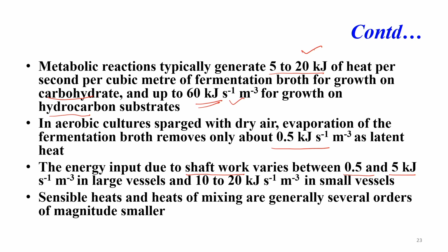So, typically the sensible heat and the heat of mixing are several orders of magnitude smaller than the heat of reaction. So, many times when we calculate the heating or cooling requirement, we can directly use delta H heat of reaction. We can ignore sensible heat and heat of mixing.